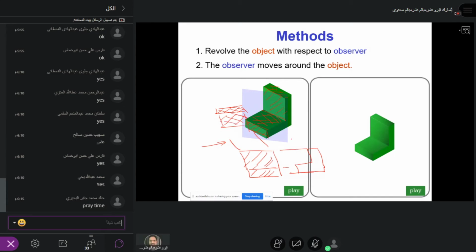All right. Now, I have seen the front view, right side view, and top view. What about the other view? What view are you asking about? The rear, the behind. Back view, rear view. Yes. So the rear view is simply a square. That's it. Because I cannot see this surface on the other side. Just imagine you are seeing from this side. All I can see is only this surface.